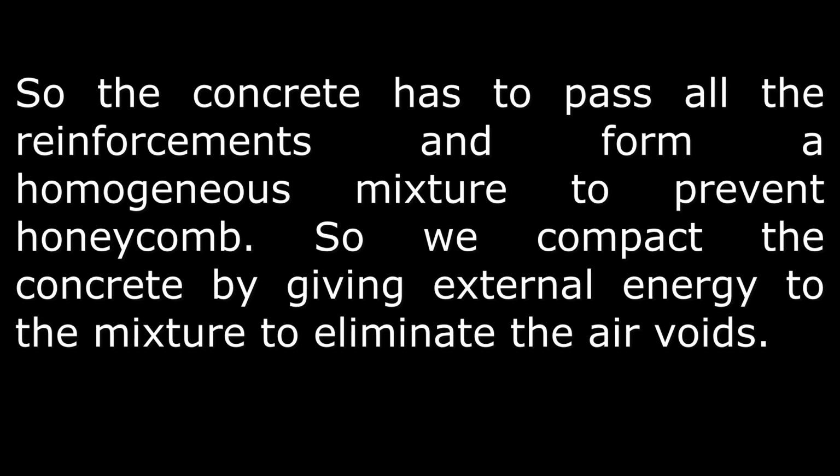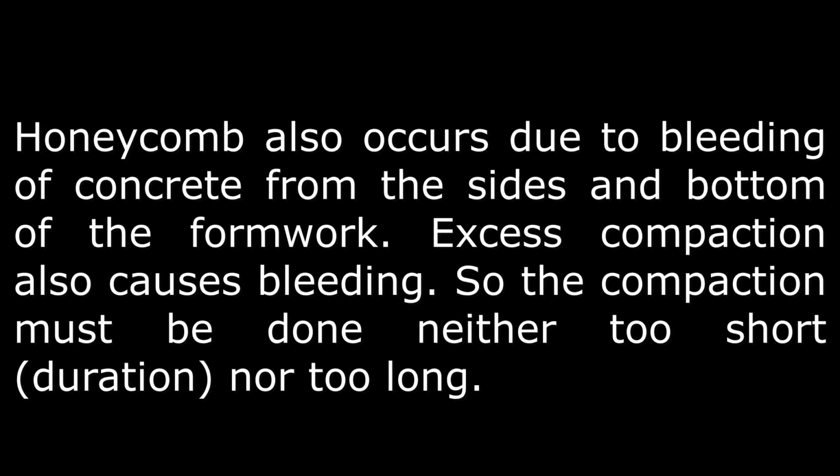So, the concrete has to pass all the reinforcements and form a homogeneous mixture to prevent honeycomb. So, we compact the concrete by giving external energy to the mixture to eliminate the air voids. The honeycomb also occurs due to bleeding of concrete from the sides and the bottom of the formwork. Excess compaction also causes bleeding, so the compaction must be done neither for too short a duration nor too long.